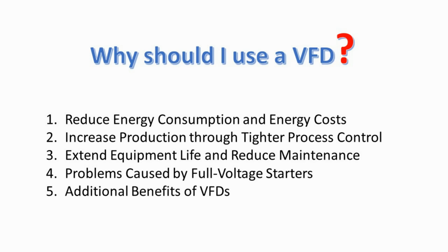Additional benefits of VFDs. In addition to energy savings and better process control, VFDs can provide other benefits. A VFD may be used for control of process temperature, pressure or flow without use of a separate controller. Suitable sensors and electronics are used to interface driven equipment with the VFD. Maintenance costs can be lowered, since lower operating speeds result in longer life for bearings and motors.